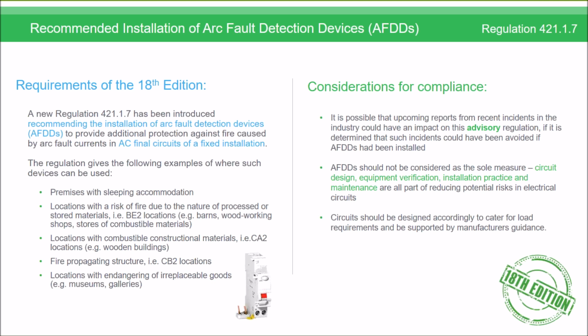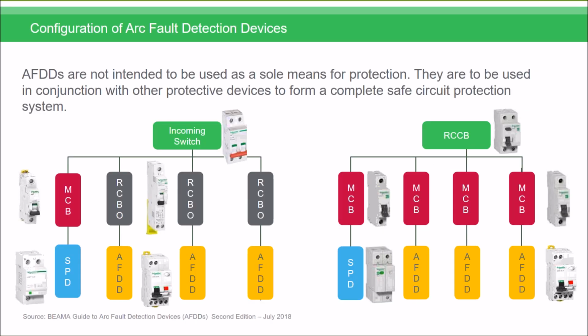So the practices around circuit design, equipment verification, installation practice and maintenance, and also ensuring that you provide full protection with short circuit, overload, earth leakage, is to form part of a complete circuit protection solution. And the circuits should be designed accordingly to cater for these load requirements and make sure that you do follow the manufacturer's guidance on these devices.